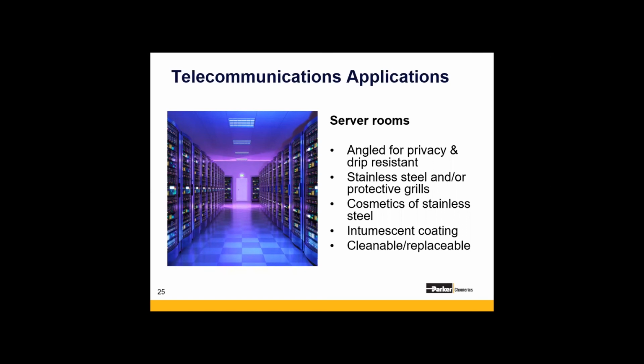And the last requirement really is that the vents are cleanable and replaceable. So being able to take off a vent, wipe it down, wash it down, remove all the dust, and then reincorporate it back into a design is really one of the driving factors for using more durable stainless steel vents.